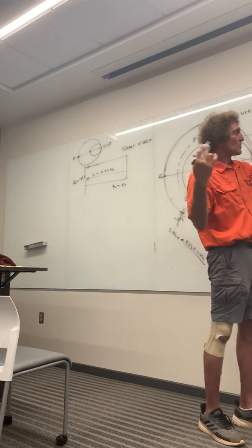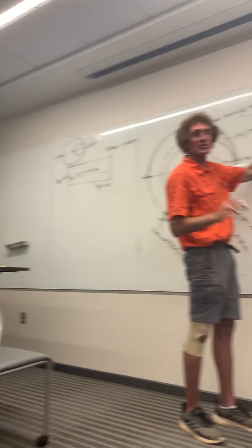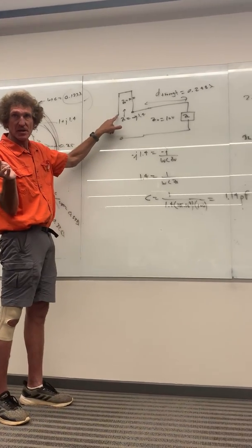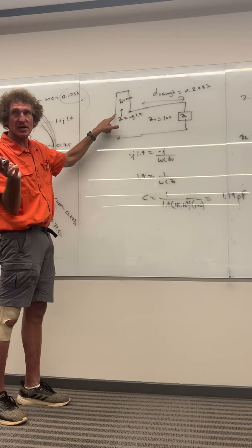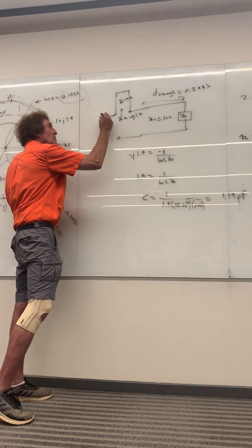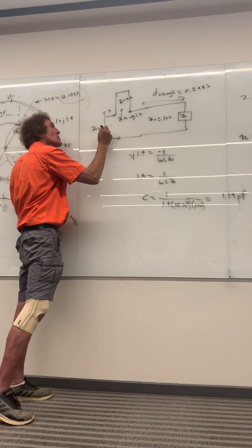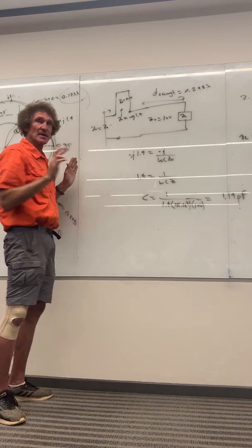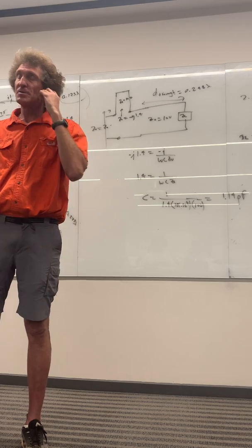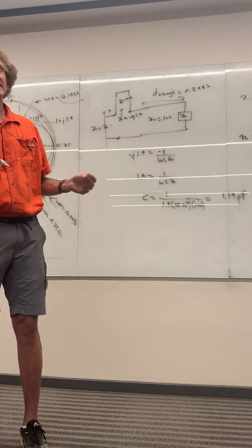And with the way techniques are, this connection will be perfect. You can do this easily. You can have 2 transmission lines, you can connect them like that. And then from here on, that Zn is equal to just Z0. It's matched. Do you follow me on this, class? So that's using a transmission line instead of an element.